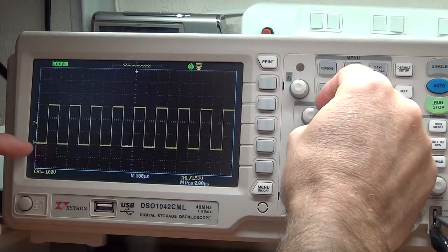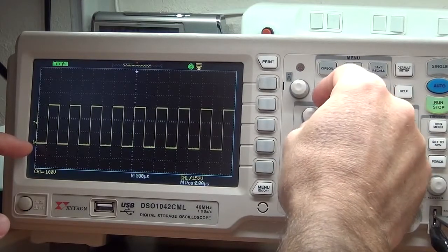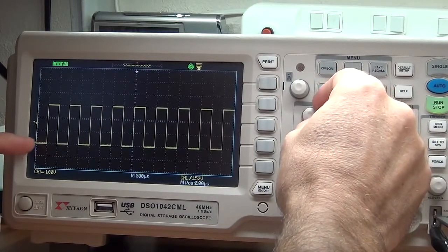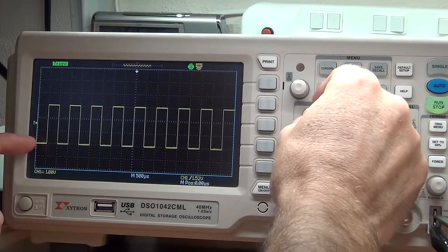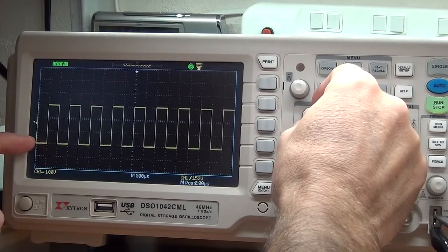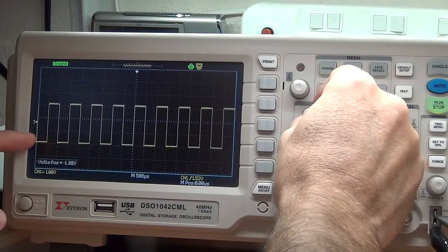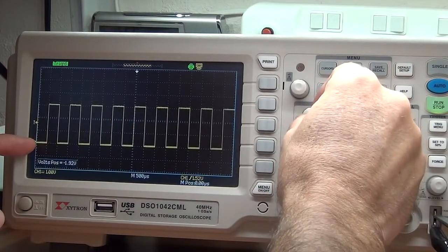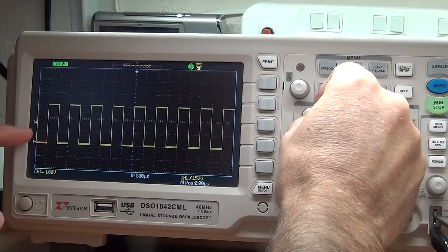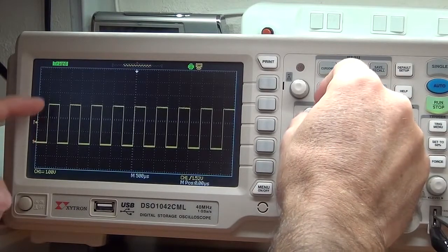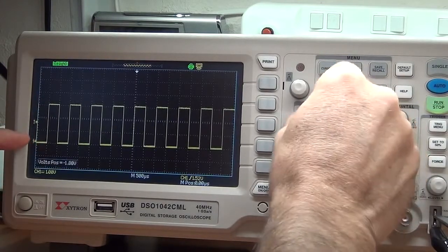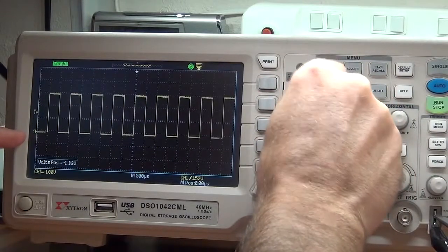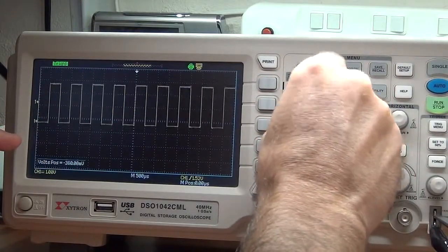You do have tools to help you make measurements, and it would be something I can show you in the second, more advanced tutorial on oscilloscopes. But what you can do is position your signal with this in place so that you can easily count or take measurements of your signal. So I could put it up on a line, and we'll put it up on that base line.